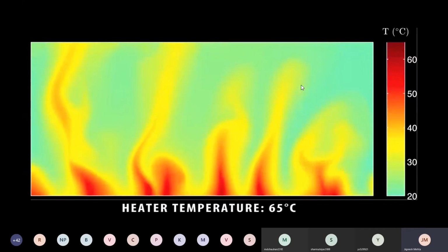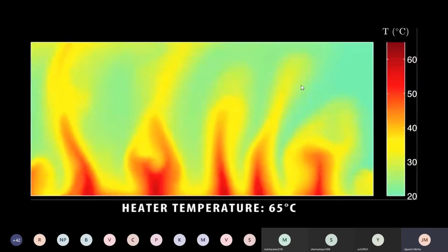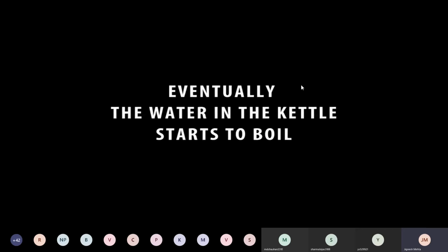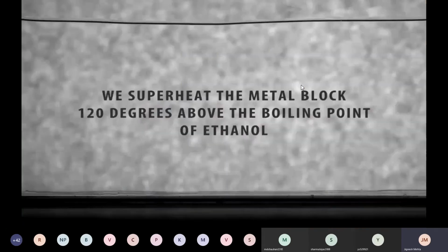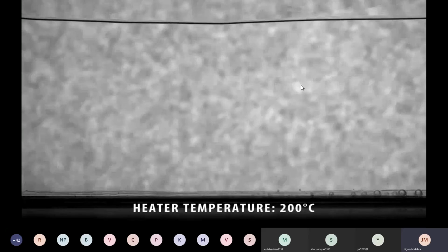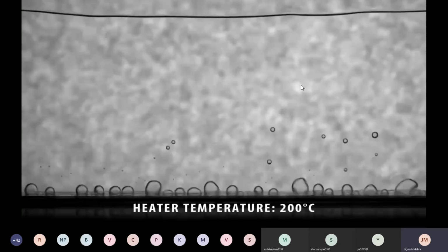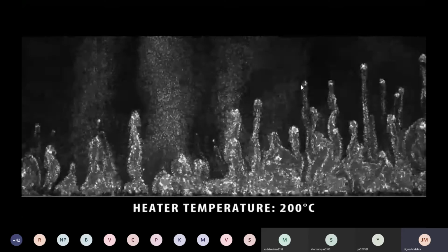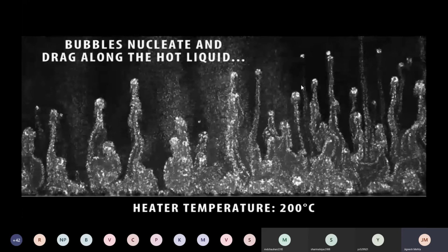This is natural convective boiling that is taking place. So actually it's not real boiling, it's mainly natural convective heat transfer. Though the surface temperature was higher, there was no real boiling taking place. Now if the temperature of the heater is high, then the generation of the bubbles is very clear, right?